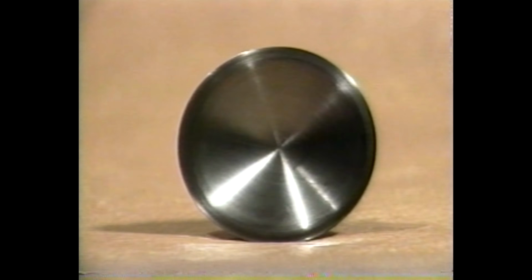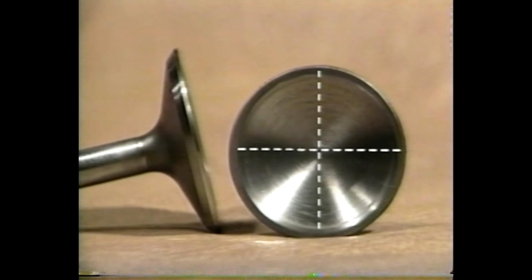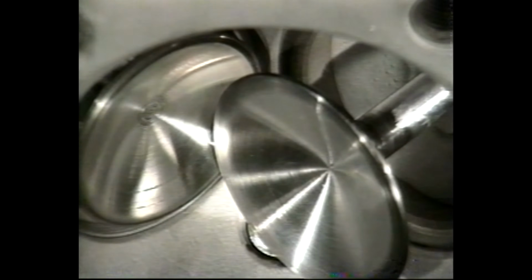As a general rule of thumb, the maximum intake valve lift in a stock Evolution motor is approximately 25% of its valve diameter. In contrast, the intake valve lift in a stock shovel head motor is approximately 20% of its valve diameter. Racing motors will have intake valve lifts that are 30 to 35% of their intake valve diameters.